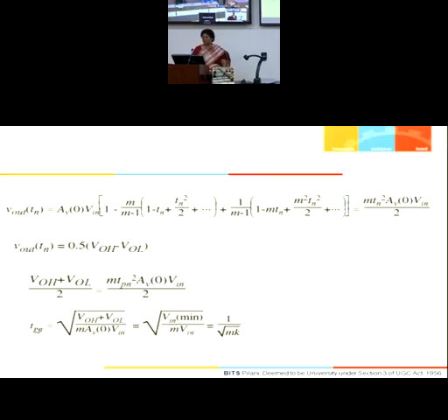So this is what you get after solving all these expressions, using the mathematical series and neglecting higher order terms. You get the Tp corresponding to a two-pole system as (VOH plus VOL) by (M AV0) into Vin. This is what is given. You can also cross check with your own analysis. So this is the expression for the propagation delay for a two-pole system.